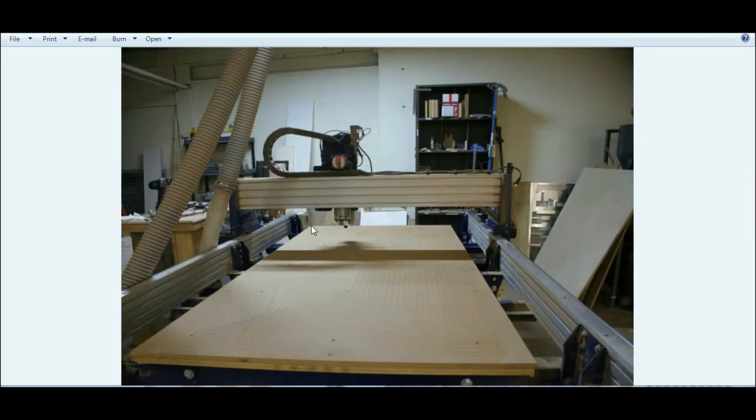So it's a full 4 foot by 8 foot. 4 foot is the Y direction. I'll definitely get into this more, so if you're a little over your head right now, don't worry, I'll get into detail of what all this stuff means. X is the long direction, so 4 foot in the Y, 8 foot in the X, and it also goes up and down in the Z. The max Z depth is 6 inches. That, of course, all depends on the bit that you have in there. If you can find a 6-inch cutter, you can cut 6 inches deep. But that's definitely a specialty bit.